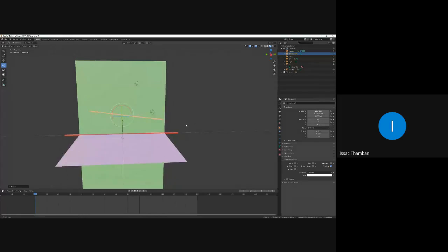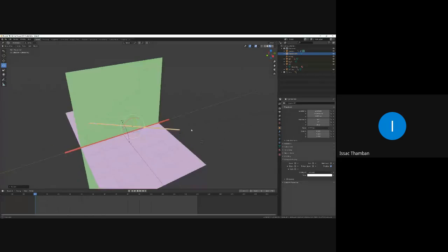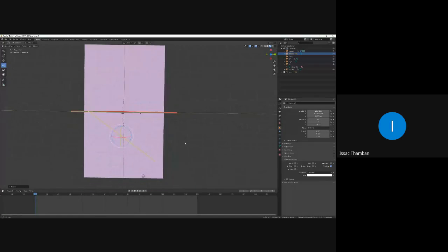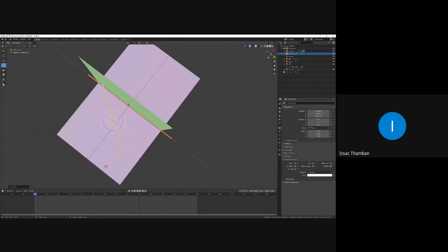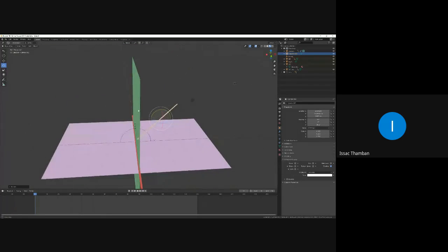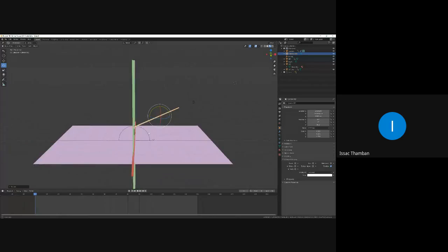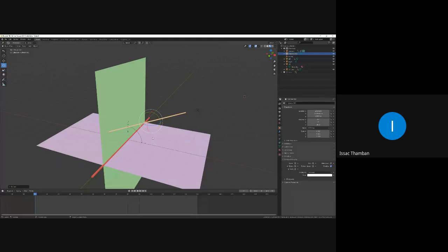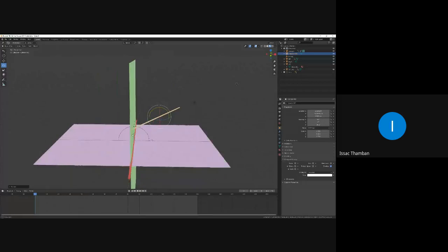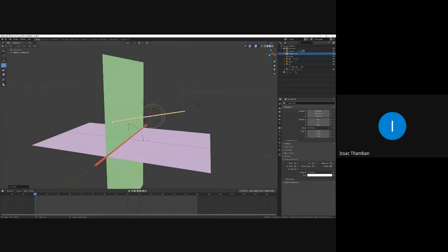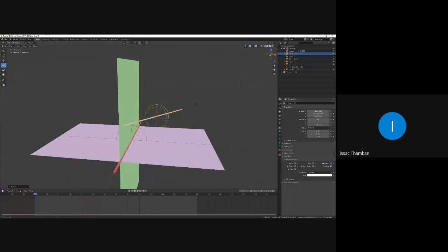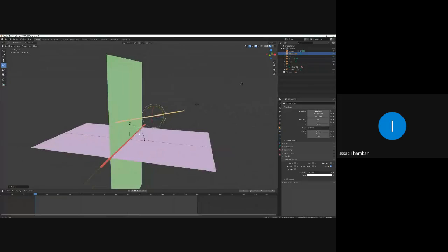But the line is inclined to VP. That means if you extend that line, then at a particular point it will penetrate through the vertical plane. So in this case, there won't be any horizontal trace, but there will be a vertical trace. Here, the line is penetrating the vertical plane at this point, and this is our vertical trace.